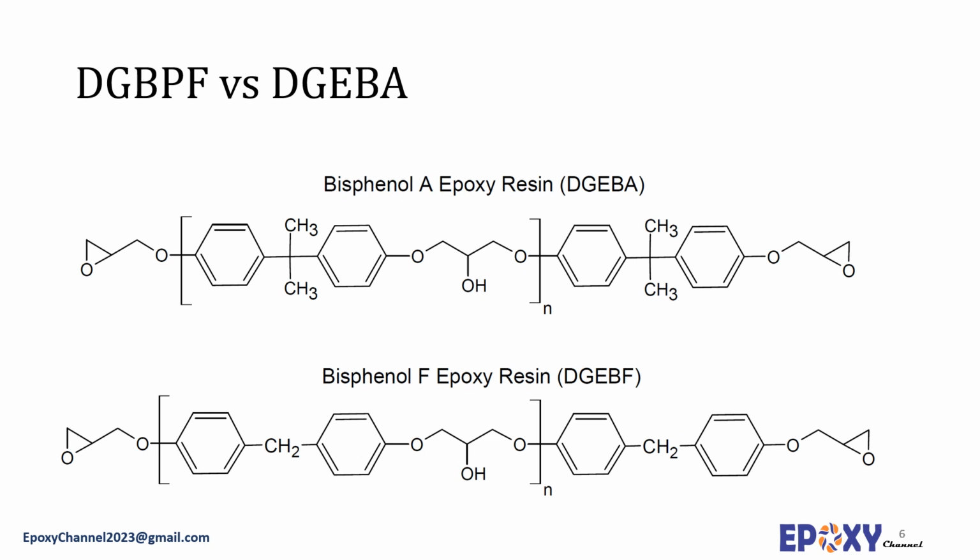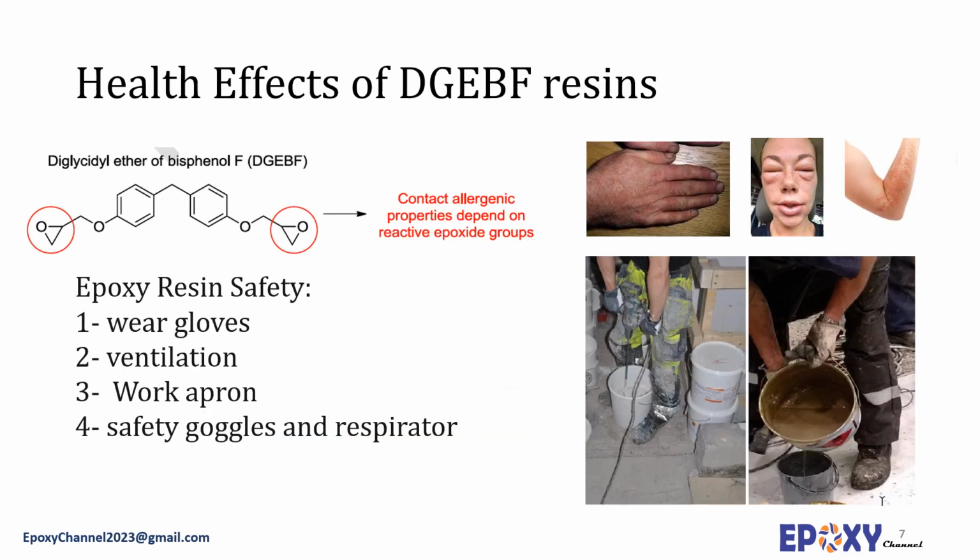It is worth mentioning that as the solid content of diglycidyl ether bisphenol F epoxies is 100%, the blend has no VOCs. Chemical products containing diglycidyl ether bisphenol F resins are quite widely used and may often be found in metal or concrete paints, lacquers and other coating agents, adhesives, glues, bonding agents, flooring products, composite materials, and injection resin used to repair concrete cracks. Some studies have shown that BPF has liver toxicity, and the health concerns regarding BPF have been explained earlier in the former slides. Here, the spot is an epoxidized product.